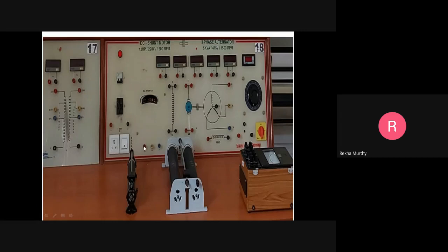And here the LFA, you can see that this is a 3-point starter. So the 3-point starter will have these 3 terminals. This is a DC starter, through which the motor will be driven. L is line, A is armature, and F is the field. Through the respective terminals we have to make the connections. And there is also the LPF wattmeter which you are going to use. Since it is an OC test, definitely we require low power factor wattmeters.